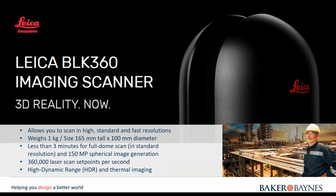It's positioned on a tripod where it's fixed, and then from there it oscillates and takes a lot of pictures, and with laser technology it picks up the scan points per position. So you get your X, Y, Z like you just saw on Recap, and it picks up the origin point by switching the actual machine on. So it's quite clever for a really small, compact machine. We've used it a lot for interior scanning, and it's quite impressive. The picture quality is great, and it goes up to 360,000 scans per second.